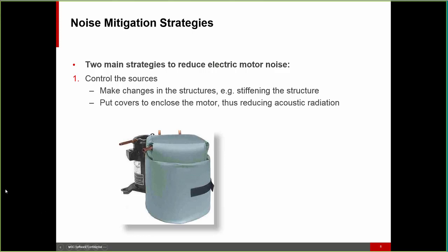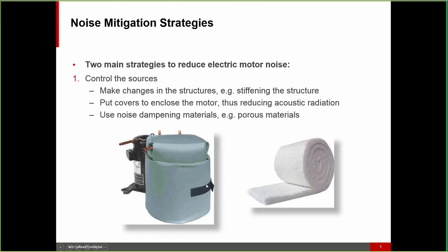Another way to control the noise is to put an enclosure around the noise source, such as this one, or we can put a dampening material, such as this acoustics foam, to absorb the noise.